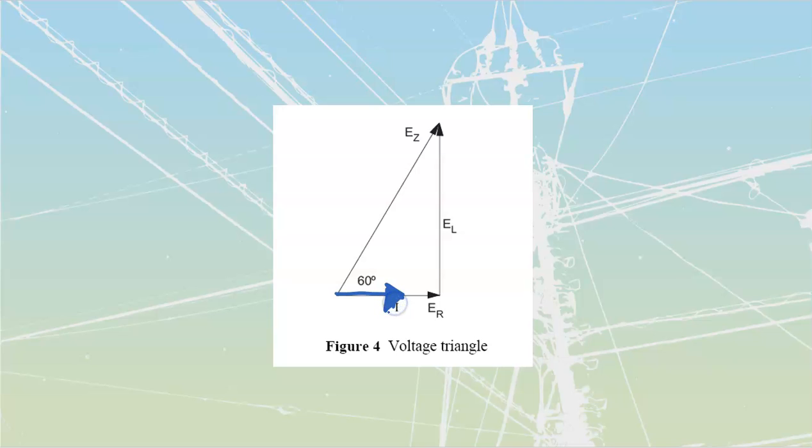Now, current is supposed to have closed arrowheads. There are vector conventions that you're going to cover, particularly in the third year where you do a lot more vector analysis. But one of those is that voltage has open arrowheads and current has closed arrowheads. They've just got a couple of errors on here because they're showing all the vectors with closed arrowheads, but they should have some that are going to be open. So I start with my current.